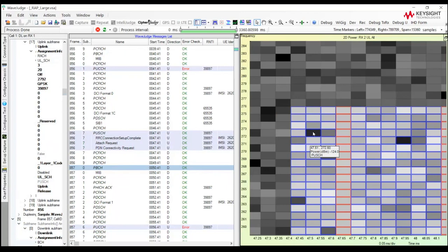So here we can find performance problems. If you're doing an interoperability test and you find that maybe one of the UE chipsets has a higher or lower performance versus the next UE chipset, this chart will tell you pretty quickly if the problem is the fact that the UE is not using all the resource elements. Because if the UE isn't using some of these resource elements, the performance of the network will go down. And you can tell clearly from this diagram that this is not a base station problem, it's a UE problem, because the UE is not using some of the resource elements.